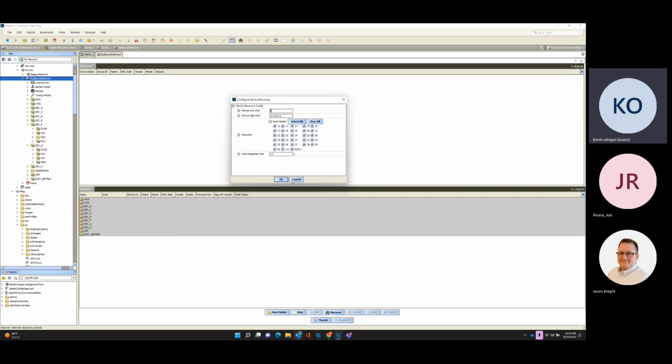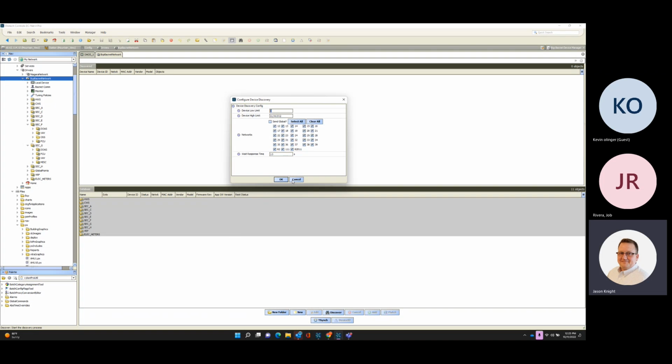So when we looked at the chillers, we saw there was an Ethernet cable out of each one of the chiller packages. So you're saying that each chiller has an Ethernet cable that then goes into the mechanical room where the unmanaged switch presides. Correct. And then from there, a single line from the unmanaged switch to the nearest IDF room. Correct.